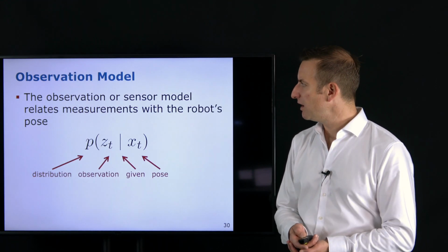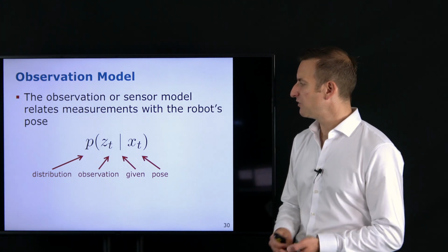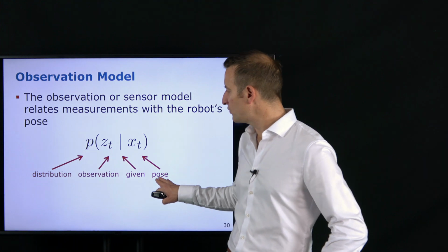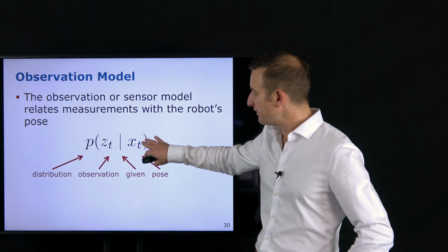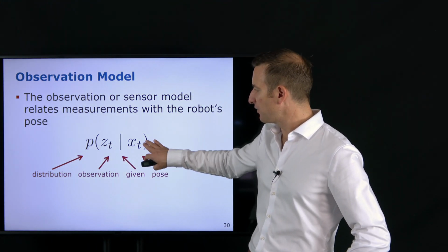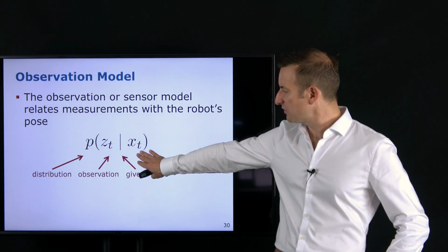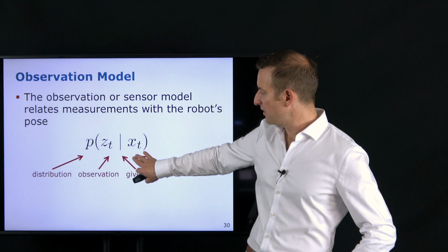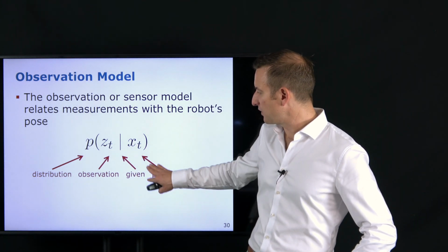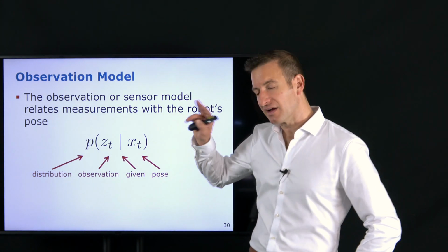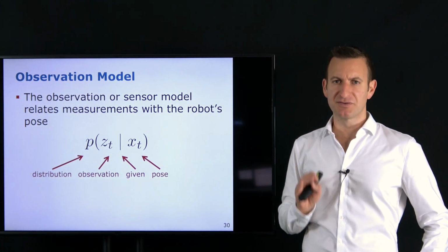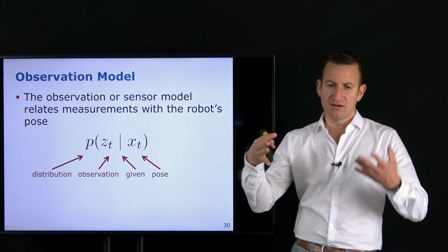And the second part was the observation model. This is basically the distribution about my observation given my pose and my, let's say, map built so far. So the map should actually sit in here, but often you describe it just in this form because this X is often used as the whole state in SLAM, your state vector. But in our mental notation you may want to add an M over here, for the map built so far, depending if that makes it easier for you.